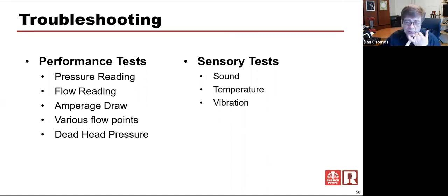What does it sound like? Does it sound like you've got cavitation going on? Does it sound like it's running nice and smooth? Is there some kind of a squealing noise? Is there some kind of a grinding noise? Whatever it might be, does it sound like there's gravel going through the pump, which would either be gravel or it would be cavitation? What temperature are things running at?